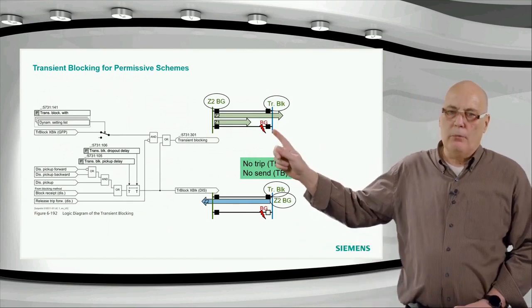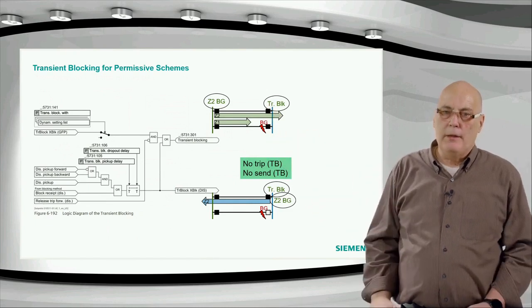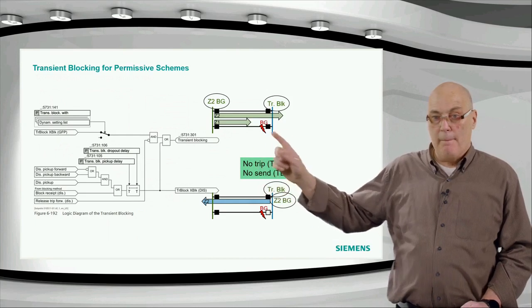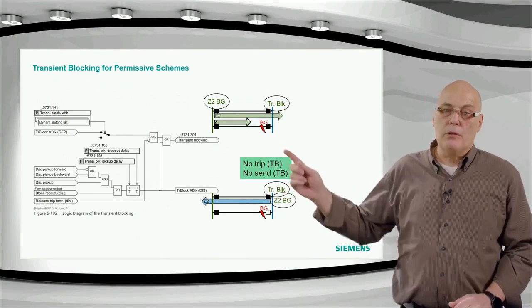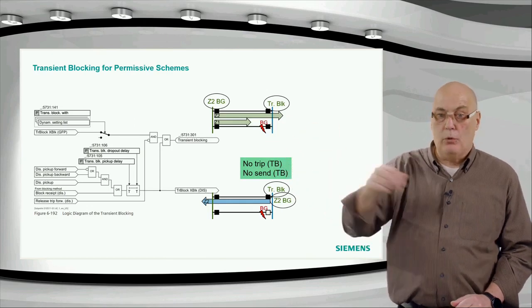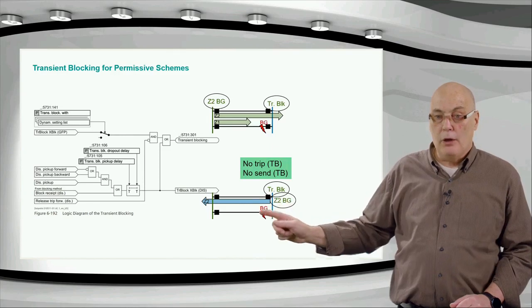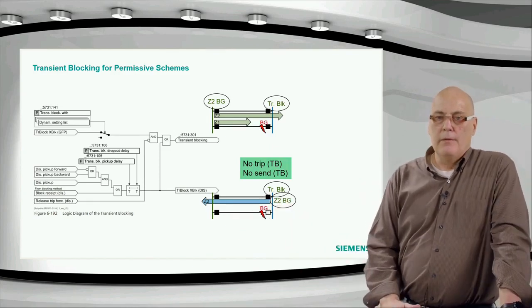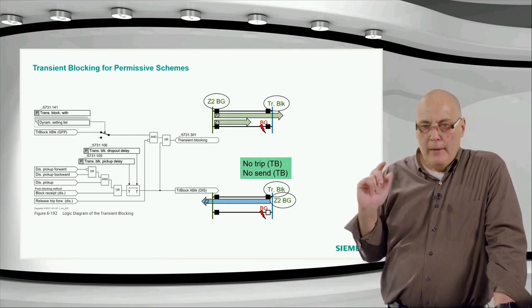At the top, for example, you can see here 2 feeders again. It does not have to be a double circuit here, but on the double circuit, this problem is amplified, or more probable, because of the mutual coupling we spoke about earlier on. During the second condition here at the bottom, the mutual coupling will pull this fault closer to the relay location. But that's just something else one can talk about, a bit technical.